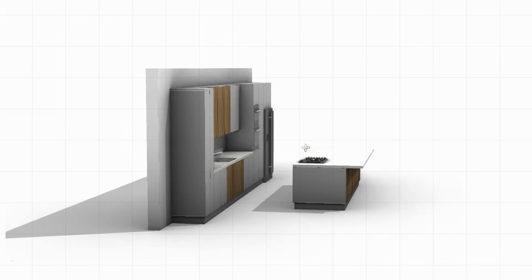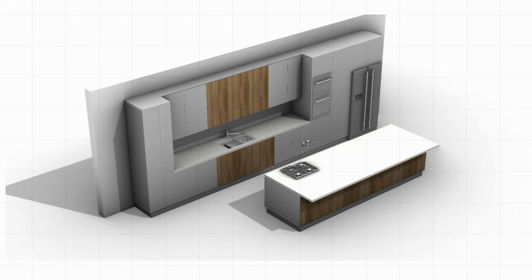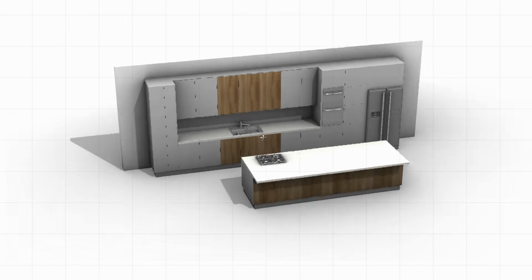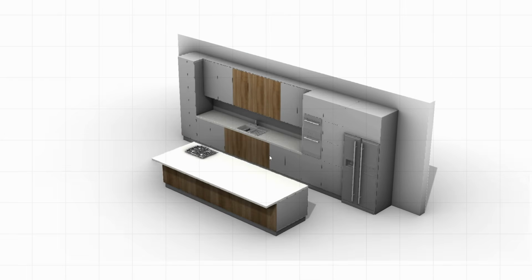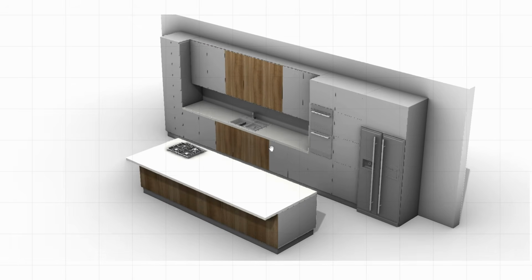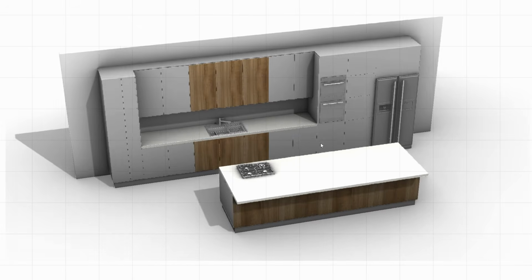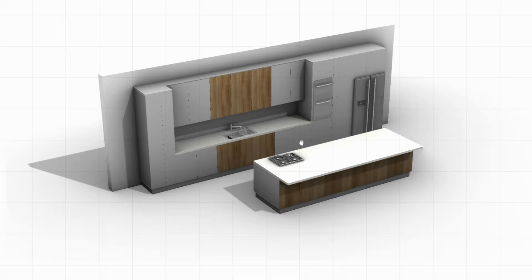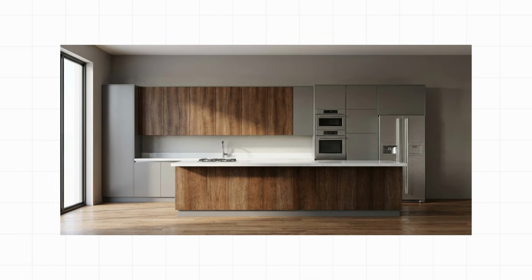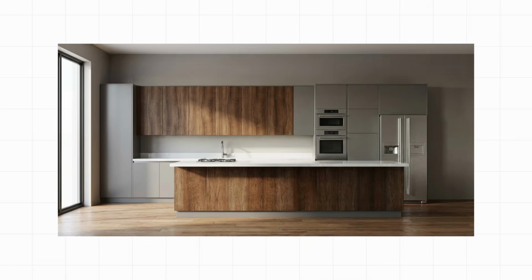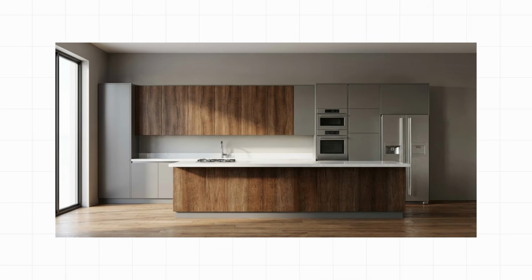The cabinet bodies are usually made from 18mm panels, which is the standard for this type of construction. For the oven and microwave, these two elements are often placed vertically next to each other, making them more accessible and creating a logical workflow for the user. Drawer and door divisions are generally between 30 and 60 centimeters, balancing both functionality and visual proportions.